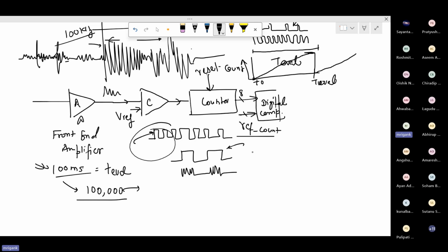So you are applying this algorithm on hundreds of seizure data. You have to make sure that for all those cases, the reference count is sufficiently high so that it is not giving false alarms for random spurious spikes like this. You can have a bunch of random spikes like this coming at any point, and for these it should not give you a false alarm. So the count should be sufficiently large, but just large enough. If you go on increasing it even after the false positives have become zero for all those cases, there is no benefit, so we'll just stop there. That's how we will determine the reference count.